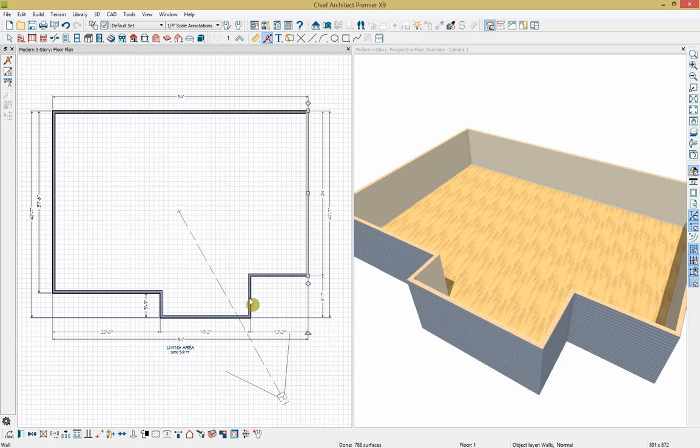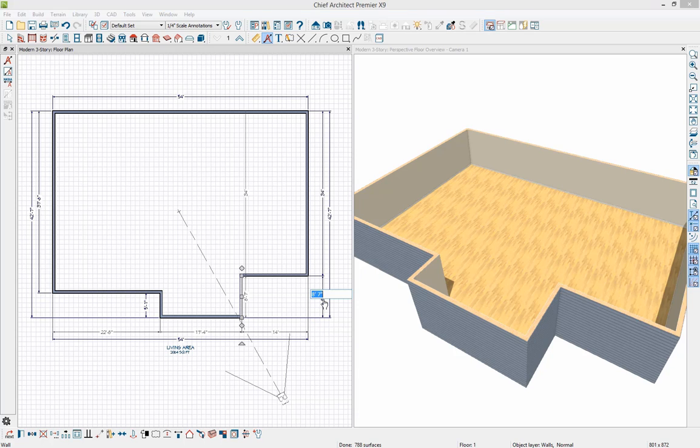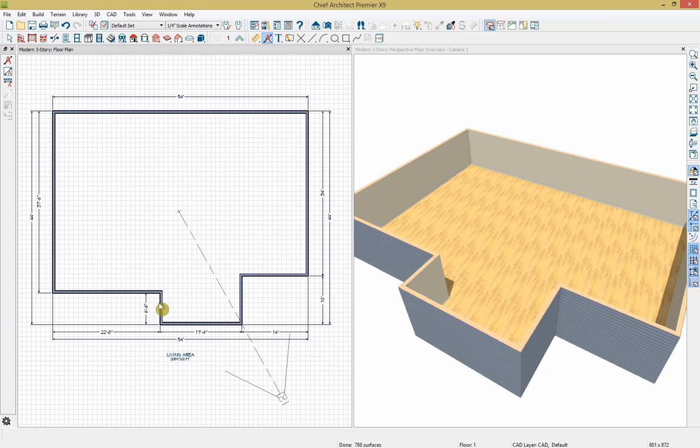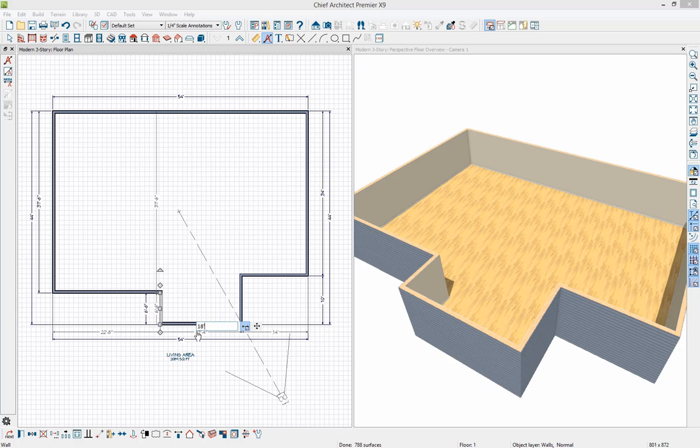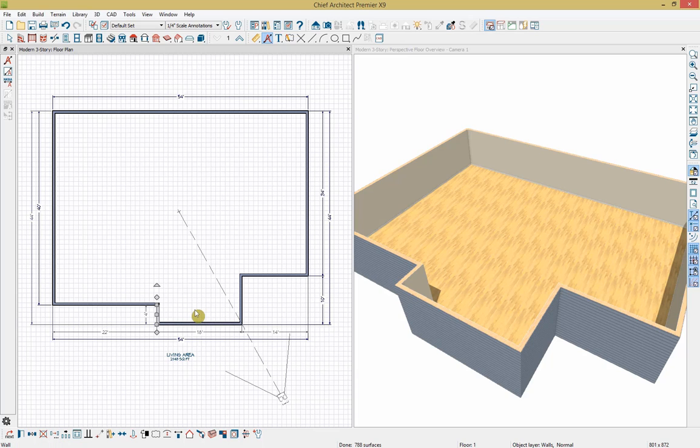With the program, it will automatically think in inches, so put the foot marker in there or type in inches as well. And we'll move this wall to 14 feet, enter, and then we can move this one to 10 feet and just keep working away. Here we'll modify this to 18 feet and this one to 4 feet. So again, just modify how that operates, and we're going to move the wall that we've selected.